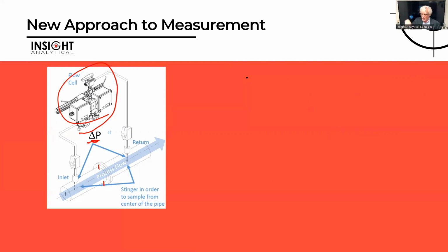Sample from the process returned to the condensate tank. And that drives flow up through the flow cell and right back down to the process. Very short line runs, so we get the fluid over there very fast, can measure quickly. That's put out near the process.